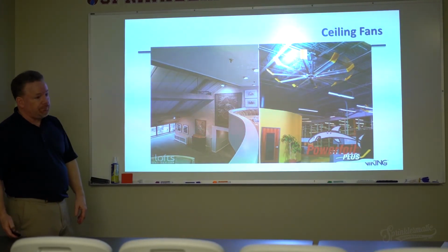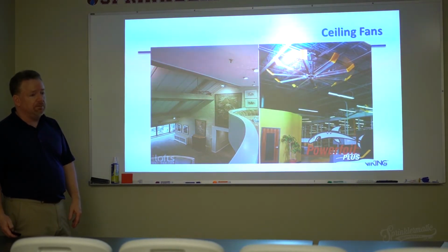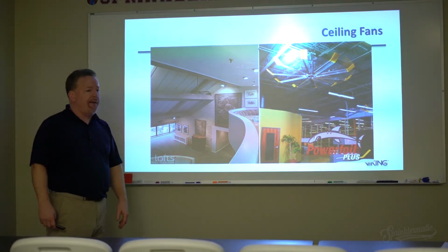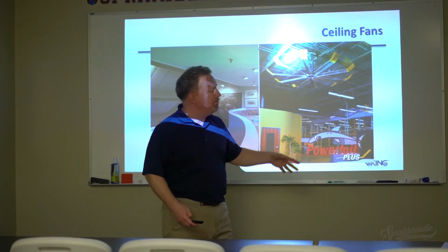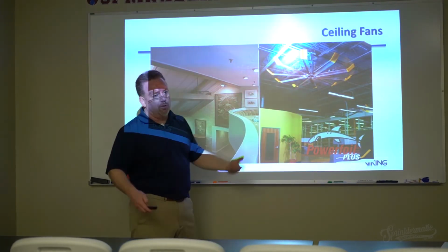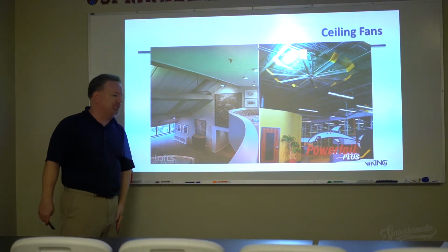That's surprising. Are they tied into the alarm system, just because they move air? Yeah, they move air, so if you get an alarm, they stop, and then they're no longer an obstruction to the spray pattern.